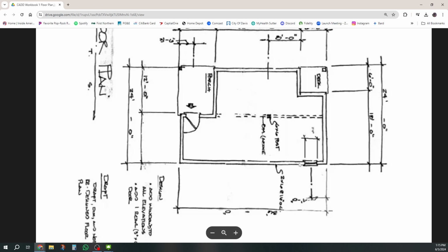So that's telling you that the framing is made out of 2 by 6s, and those uprights, the studs, are every 16 inch. OC is on center. And there's some sort of a little window here that's centered 4 foot away from this outside wall. So that's kind of what we know, and we're going to try to draw that.